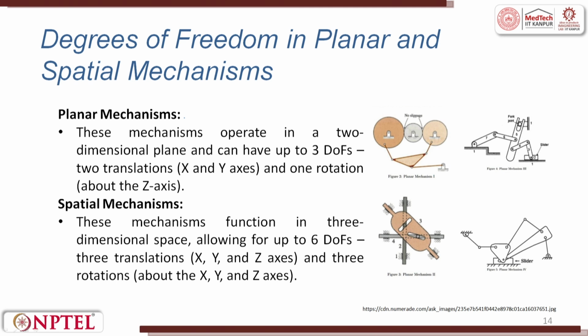The planar mechanism is a mechanism which operates in a two-dimensional plane and can have up to 3 degrees of freedom, that is 2 translations and 1 rotation. Okay. So, you see here there is a gear, there is a gear, there is one more gear. It is attached to a structure where you have links, and this in turn is fixed. So, here you can have a movement in a plane.